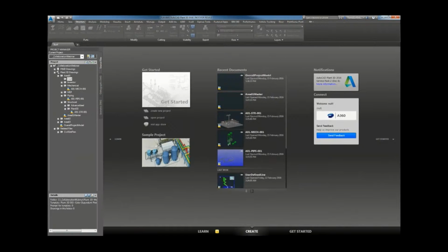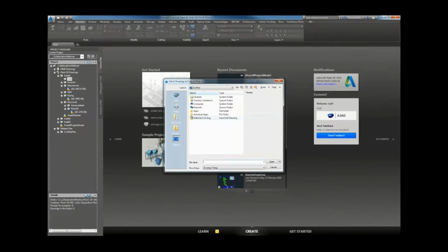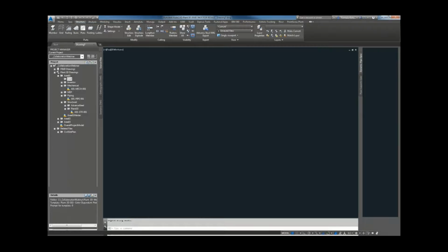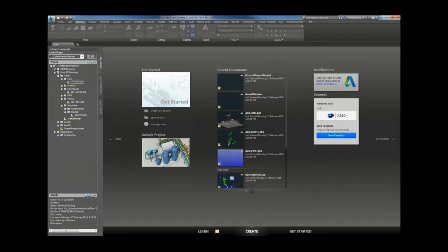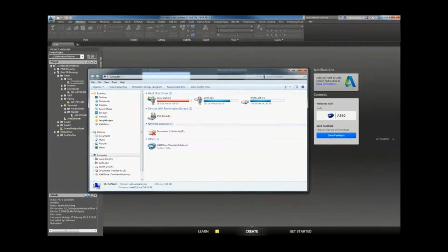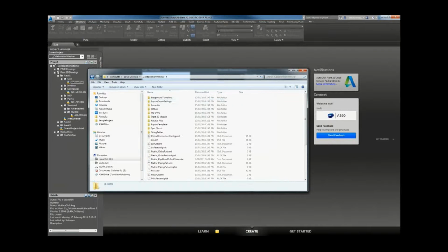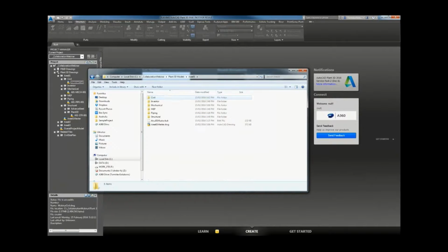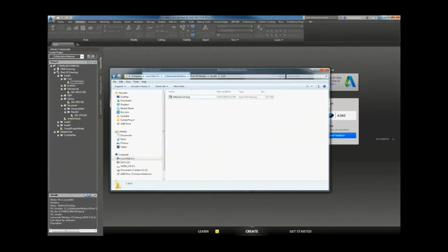I'm going to jump back into Plant 3D, and what we're going to do is we've got a couple options here. I can copy the drawing to the project. So I'm going to copy that civil drawing in. Now what that means is that that model is now part of the plant directory structure, and it just means that anyone working on that civil project will need to navigate to the directory they're working in and work from there. So that's where your main civil people will work.